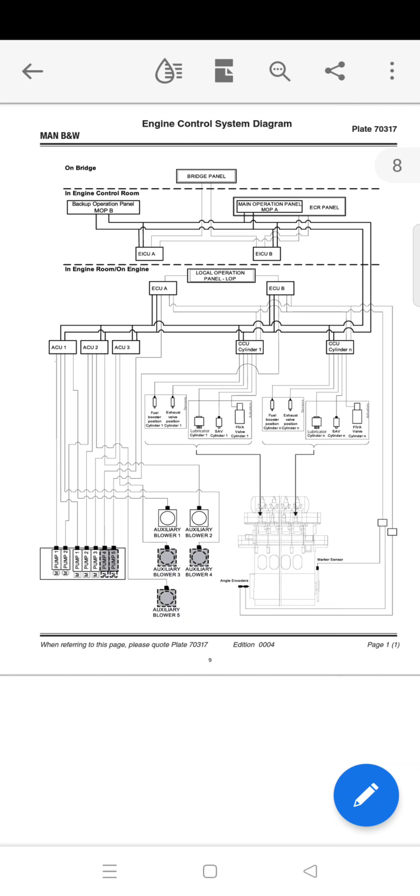All of the CCUs are identical, and in the event of a failure of the CCU for one cylinder, only the cylinder will automatically be put out of operation, running with cylinder out of operation.